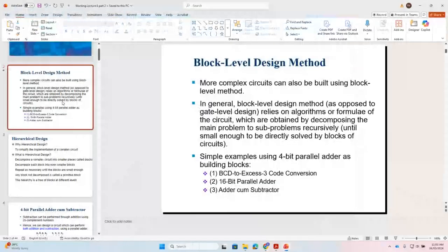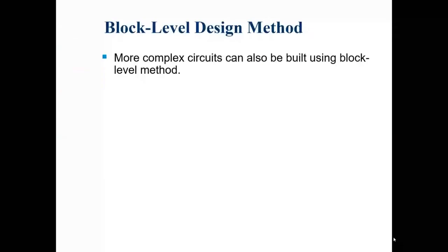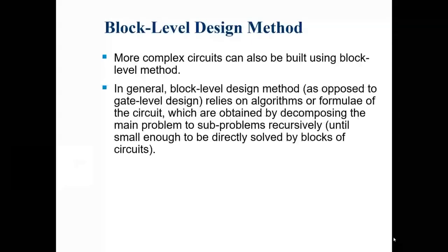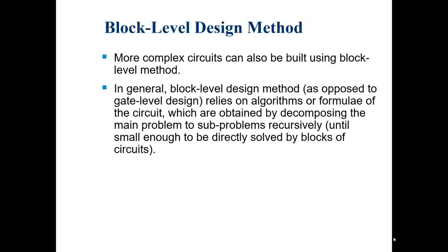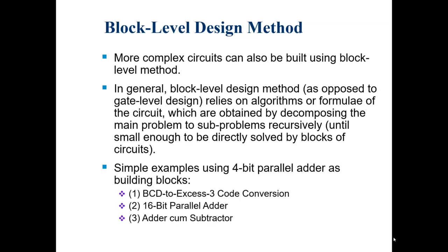In the block level design method, we rely on the algorithm or formula of the circuit, which is obtained by decomposing the main problem into sub-problems recursively until they are small enough to be directly solved by blocks of circuits. We already covered this in our last lecture. When we want to design a big circuit like a 16-bit adder, it can be designed using small blocks of 1-bit full adders. This is how we did it in the last lecture.